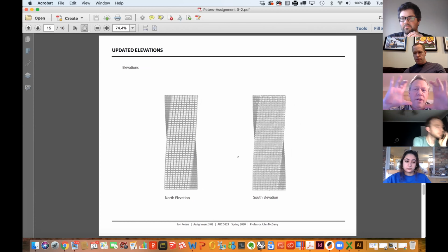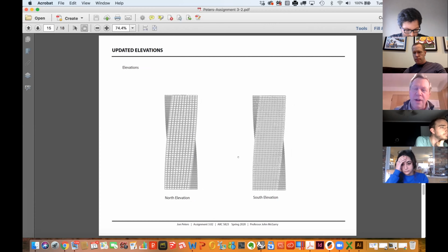You don't necessarily want narrowing. You simply want to block the sun. Okay, and so in reality, the correct panel for the south would be one that prioritized an overhang. Whereas on the east and west, where you get direct side-to-side sun, you don't necessarily want more opening. You want to do side shading so that you blank off part of the sun angle from that